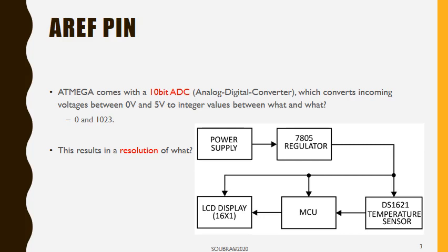So in between the minimum value and the maximum value, I have a bunch of steps. Make sense? How do I get this particular step width or length? Doesn't really matter. All I have to do is what? Divide the 5 by 1023. All right? So I dispose of 1023 numbers. I'm going to divide them on the 5 volts that I'm trying to represent. Any number between 0 and 5. Make sense? This gives me the what? The length of the step.